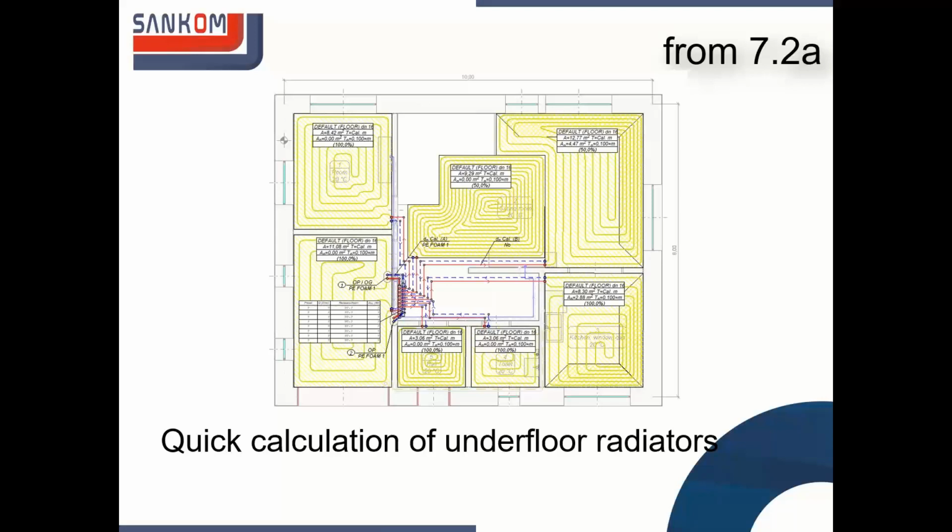And to obtain reasonable results, the program demands complete data. So at the beginning, it may happen that the program says that there are some problems that don't allow calculation. For example, if you draw a pipe and you don't connect anything, the program says it's not complete, you cannot do this full calculation. However, this quick calculation you can do anytime.